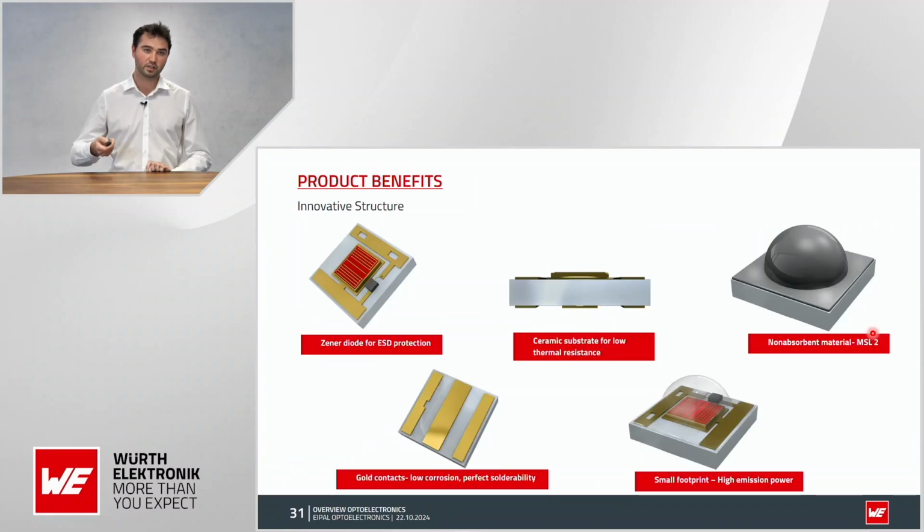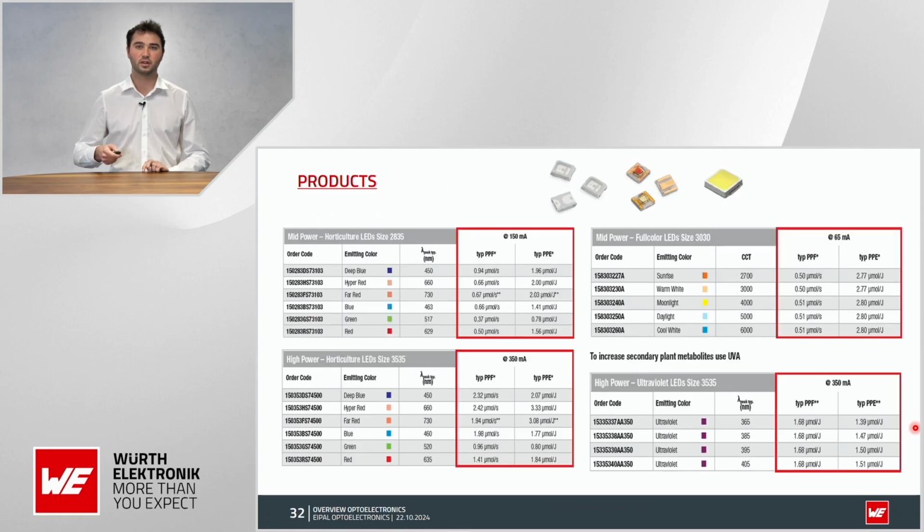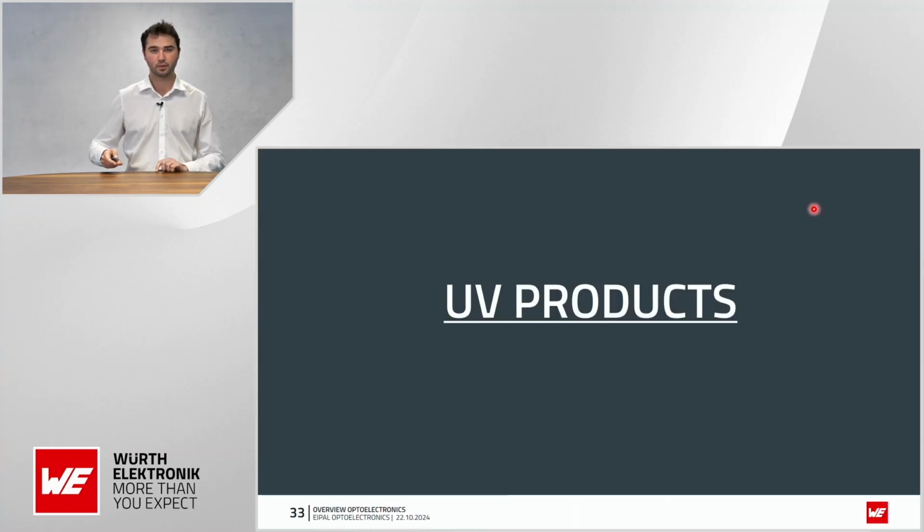Because horticulture LEDs are used for illuminating plants, of course you need a little bit higher power. This is why we typically use this ceramic type of package for this. But we also have a few EMC type packages that have a little bit lower power. They are more cost effective, but you cannot put through so much power.